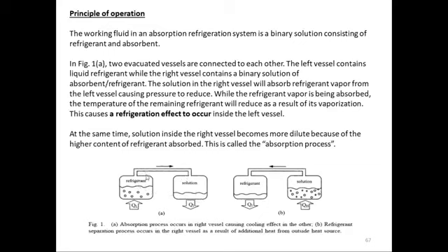When the water vapor leaves from here, what will happen to this vessel? If the water vapor moves out from here and goes into the lithium bromide salt, then there will be a low pressure created. So more water vapor will try to escape from here. Hence the temperature of this vessel will reduce. That's the refrigerating effect produced.